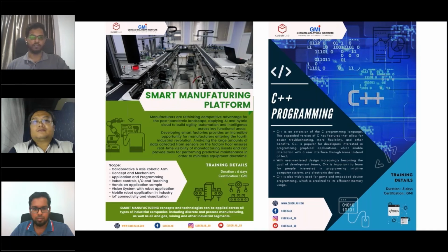And there are a lot of different brands in the market such as Cognex, Keyence, Halcon, SICK, almost any of the sensor brands have a vision system. They come with a preset of tools which we can use, such as, like I mentioned, measurement, object recognition, all those things. As for the robots, they actually come as a bare robot. There are one or two types of robots that come with built-in vision, but those are very basic. So most of the applications we do for customers, we always use external vision.